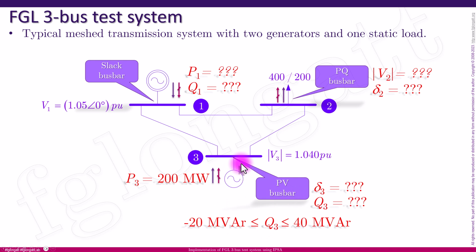And I am saying this right now because in the video you will realize that when we run the load flow, generator 3 will go to 40 MVAr, and that means that it's reaching the maximum reactive power, and the voltage will drop from this. Because in a real power system, when the generator reaches the maximum reactive power, we lose the possibility of controlling the bus bar voltage, and in those cases, the generator changes from PV operation mode to PQ.